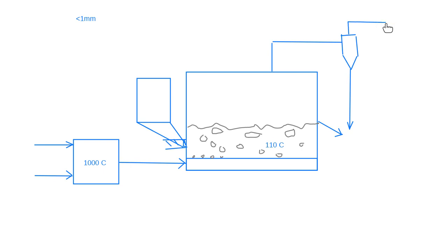So it's not very inefficient because you had 1000 degrees C and you're letting it out at 110 degrees C instead of ambient, which is 25 degrees C. So you're not losing a lot of energy doing your drying in a fluidized bed dryer.